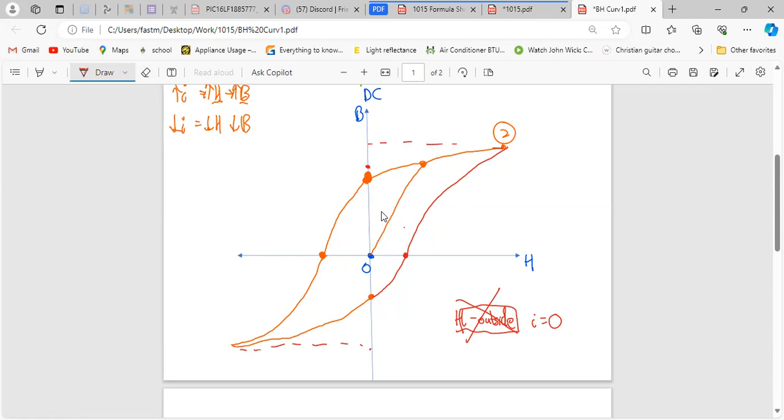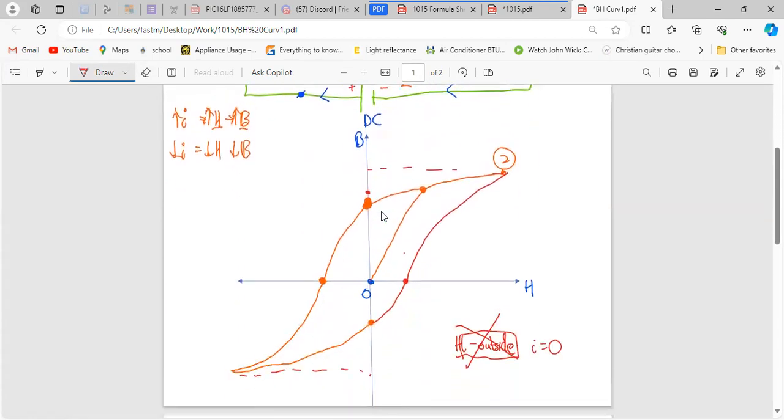Yeah, and after the saturation now, we do the same thing: we cut the current, go back, maintain some, and you keep going with the current in the opposite direction, and it's still going to happen. Same idea going on. So this is what you call a hysteresis curve. That is all that's happening in the material, and it's due to the dipoles in it.